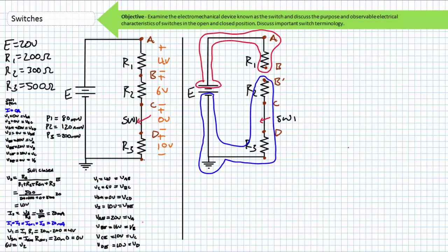Consider the difference between nodal voltages of this faulted circuit and our normally functional circuit employing a common reference. Ordinarily, we'd expect both the bottom of R1 and the top of R2 to be at 16 volts with reference to ground. However, with an open between the bottom of R1 and the top of R2, the bottom of R1 is 20 volts higher than our ground reference, and the top of R2 is 0 volts higher than our ground reference. The point is, there's a difference between our observations and expectations, and your knowledge of basic series properties can quickly pinpoint the nature and location of this fault.